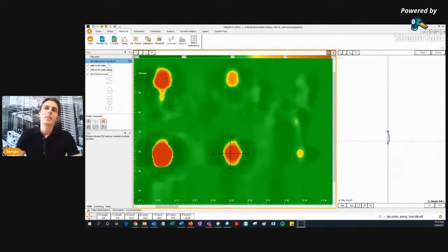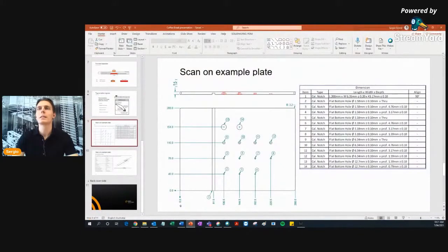I didn't focus on the voltage value we had, but I think we have something like we had before, 1.2 maybe. Now we are down at like 0.8, so we lost some amplitude of the indication, but the phase is still very similar. So we're around 91 degrees, and since the sizing curve is based on the amplitude, we still get the similar sizing of 3.2, 3.3, 3.1. If we take this one, 4.7, and I think we should be around 4.76.